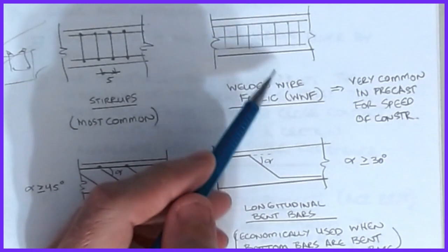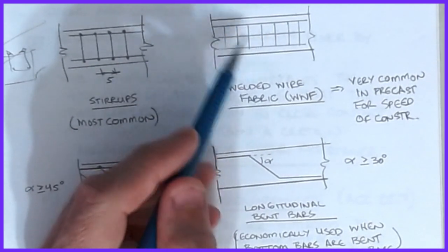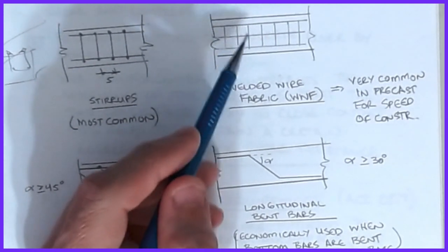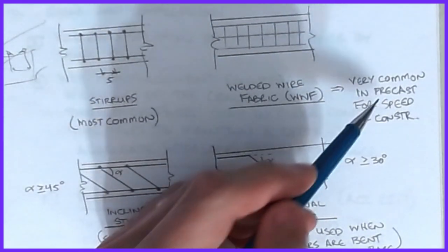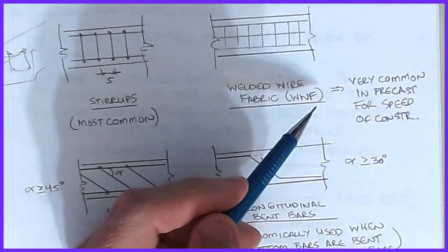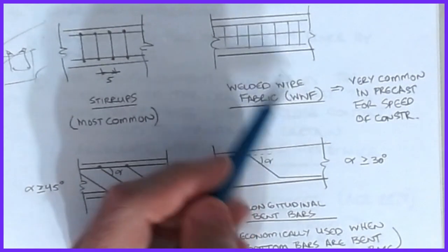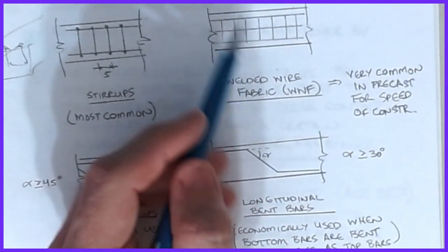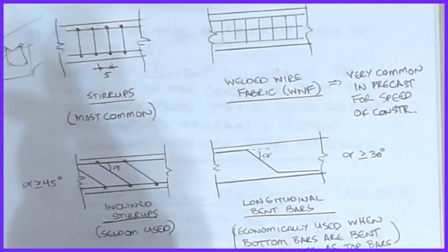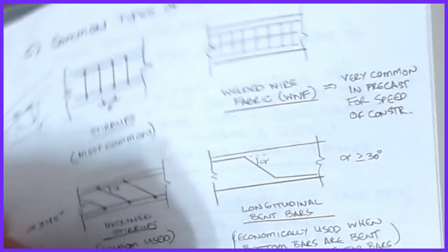And typically the shear values required for Vs are a lot smaller than this, because most precast operations are obviously pre-stressed, and that greatly increases your shear capacity and reduces the amount of steel that you need. So that's another method.